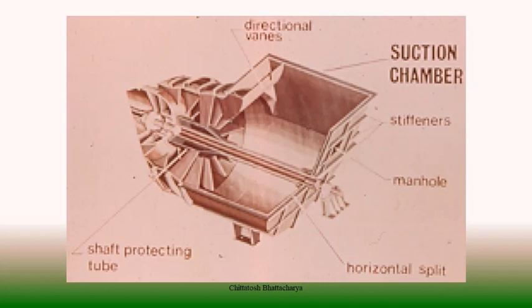And in fact, whether we operate the inlet guide vanes or inlet dampers, the flow restriction is from 30% to 70%. Beyond 70%, the flow is 100%. That means when the opening of dampers is 70%, the flow is 100%, and when we go for complete closing of the dampers, even then there is a minimum 25 to 30% flow. So control is basically within a range of 30 to 70%. We don't have it beyond that.